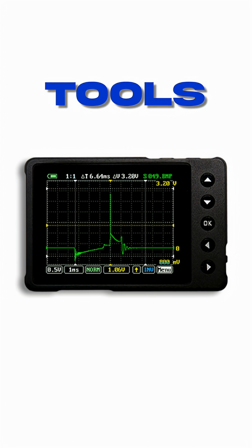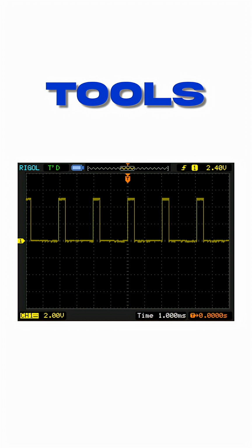To do this correctly, you must use an oscilloscope. This is one of the only ways to accurately confirm duty cycle waveforms, as it will show you duty cycle, frequency, and waveform shape and quality. You can infer based on the voltage average on a multimeter, but this could really bite you in the butt and send you down a rabbit hole. I even have a multimeter that displays duty cycle, and I rarely ever use this approach.